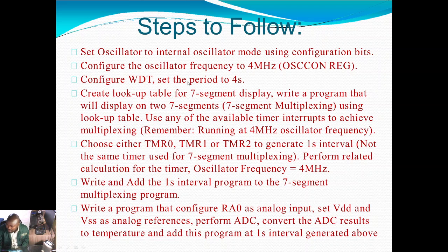So you use a watchdog timer to reset a system if it is stuck for more than 4 seconds in a particular location where you haven't found out what the problem is, or you haven't even realized that there's a problem there. Right, so let's now configure the watchdog timer.